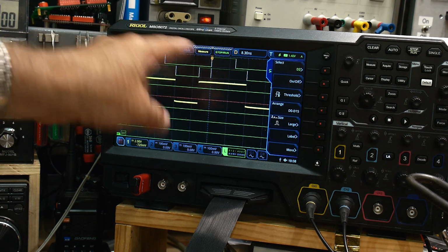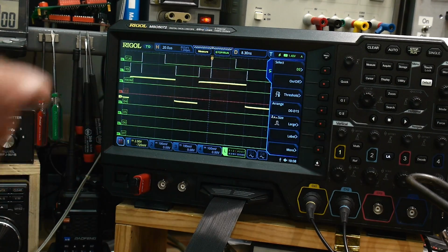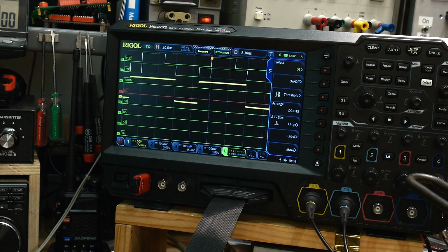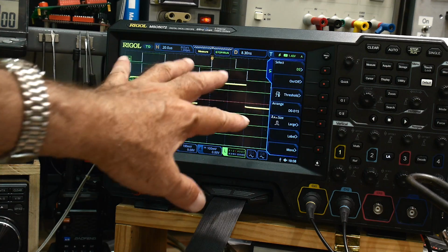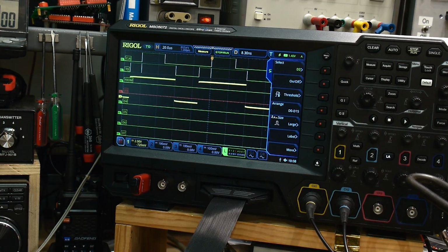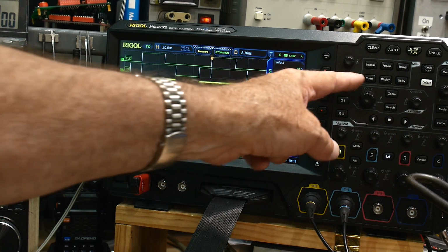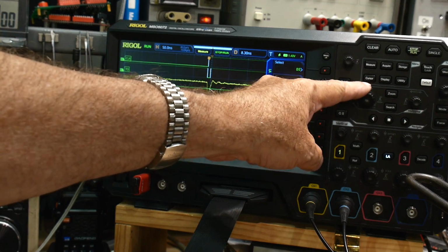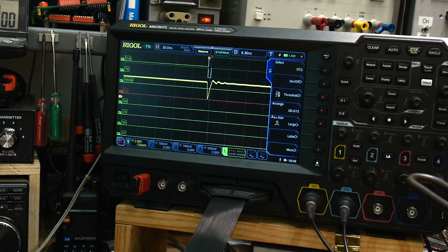The logic analyzer saw something that the analog trace did not, on a digital oscilloscope, right? And so it pointed me to this weird glitch here. Let me hook up the other clock phase. Let's see, where was my other probe? So you can see that it's kind of even dirtier there.